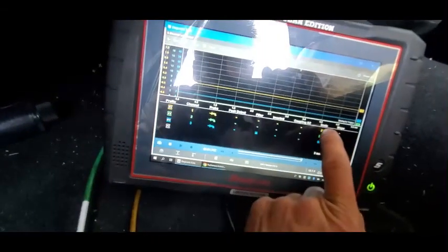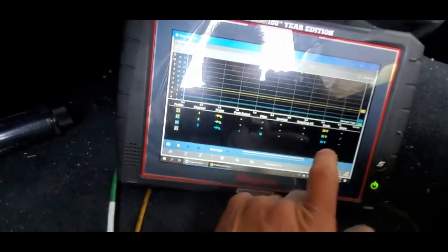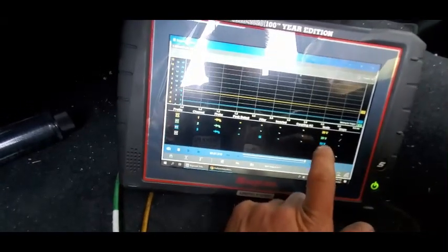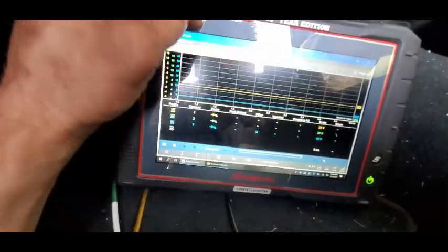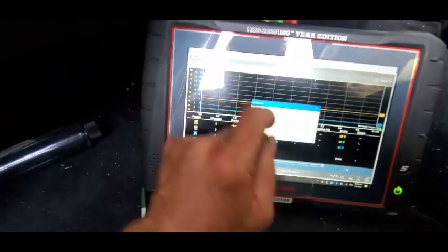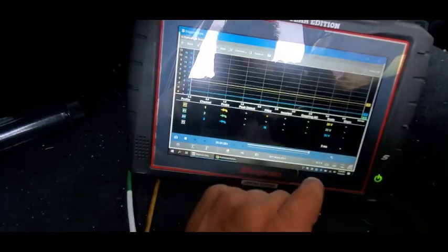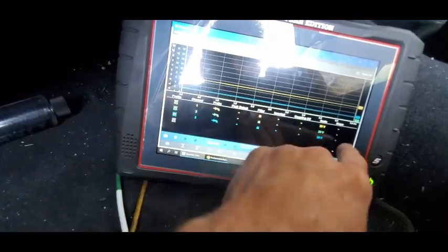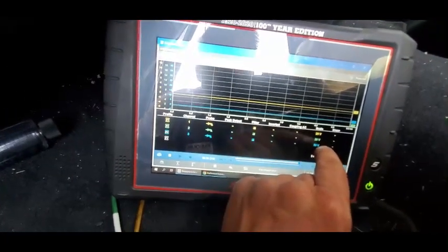Now our yellow, we're going to set it to a 20 volt scale. That's our positive to the pump. Our green is also on a 20 volt scale. Do I have a trigger on? I do. Let me turn that off. Setup trigger: none. We don't need a trigger. I suppose I could put a filter on all of them just to keep it clean. So 20 volt scale for positive and negative, okay?